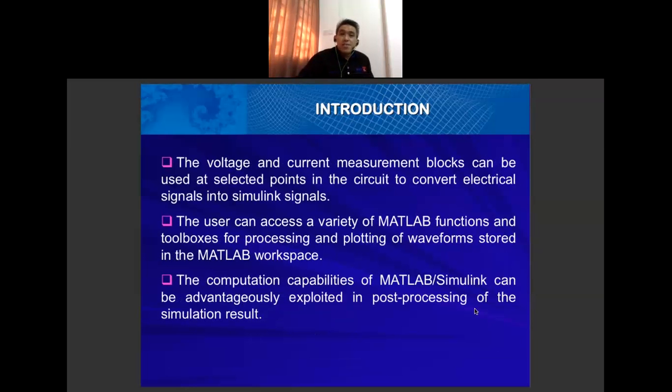Voltage and current measurements can be used at selected points in the circuit to convert electrical signals into simulation signals. The user can access a variety of MATLAB functions and toolboxes for processing and plotting of waveforms stored in the MATLAB workspace. The computation capabilities of MATLAB can be advantageously exploited in post-processing of the simulation results.